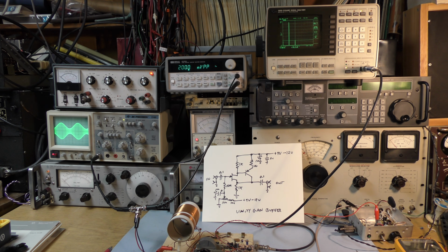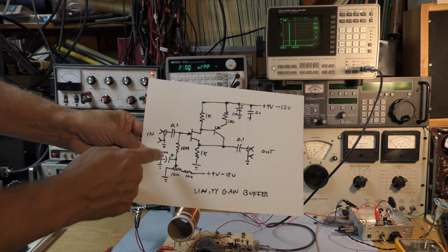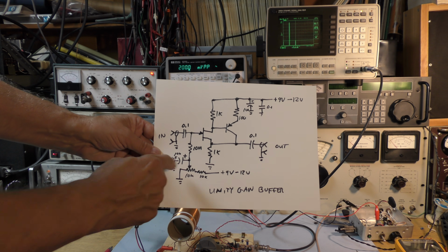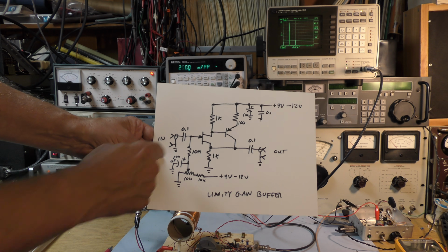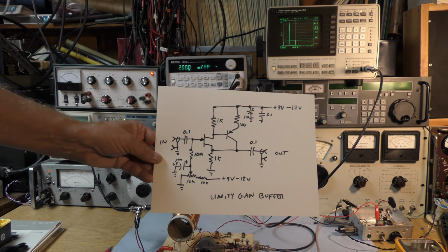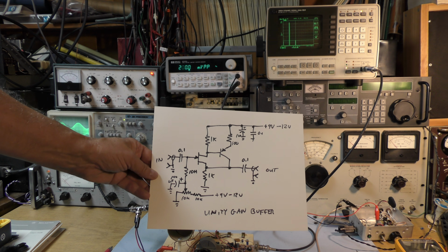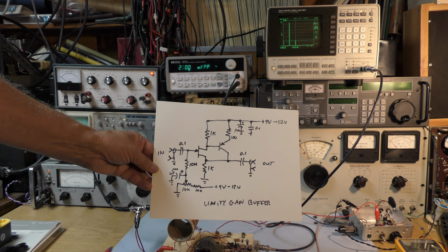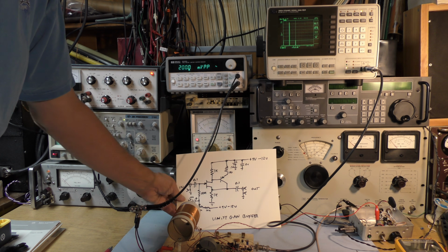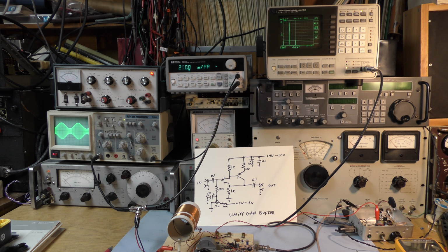Also, the unity gain buffer had a little bit of distortion on it. So I ended up having to tickle the 10 meg resistor with a little bit of bias. As soon as I got around a volt or so on the bottom of the 10 meg, the output straightened right out. So the other buffer worked, but it had some distortion, and adding this bias reduced the distortion. And that's what we're trying to measure, so that's a more complete schematic of the unity gain buffer that I'm using to have an FET probe on the diode.